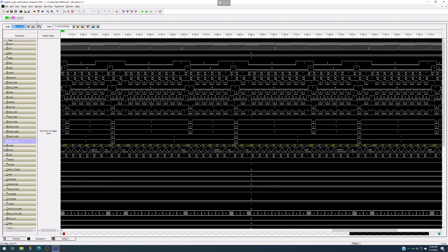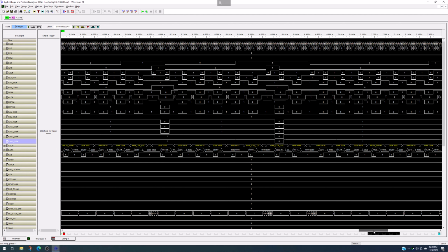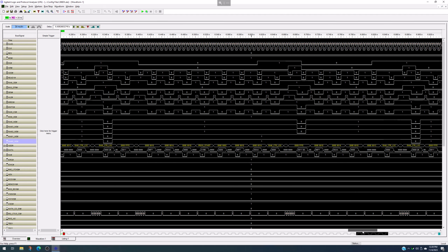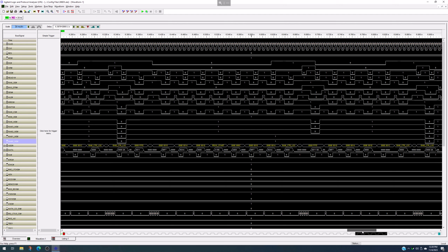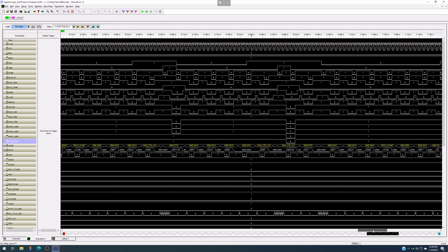That lets me put in these friendly labels, and that's a way to build my own decoding as I get into this. Or if I start having other things I'm looking for, I can add all of those, and I'm assuming I can also colorize things a certain way. That just helps me quickly pick out where my program is starting, where the RAM address is, where there's something else going on. I could even do decoding on the data and look for, I suppose, opcodes, and have it show which opcodes are being read or used by the CPU. So there's quite a bit here that I need to learn how to work with, and see what I can get out of this.